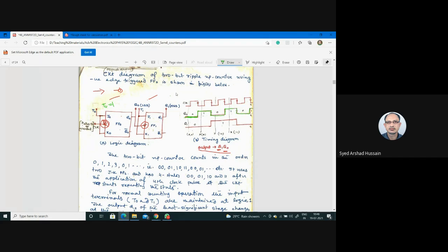Okay. Now this is our clock pulse for this circuit. We have connected like this, and again we have given an arrow here just to say that this is negative edge triggered. So Q1 was 0, and it continues in the 0 state until the negative edge of this Q0. So here you see this is 0 till this edge, then again 0, and it will go on up to this edge like this.